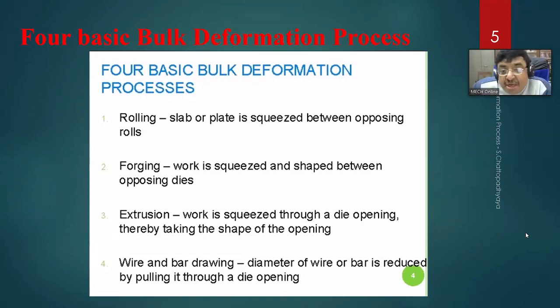In our Shalimar Wire Industries Limited, we have a continuous casting line at Nasik. Nasik provides us the rod product from the continuous casting line. Then these rods are fed into the wire drawing machine, and depending upon the diameter of the wire, that kind of stage determination will be there. And the wire drawing people know very well how many stages will be required for that reduction. Clear?